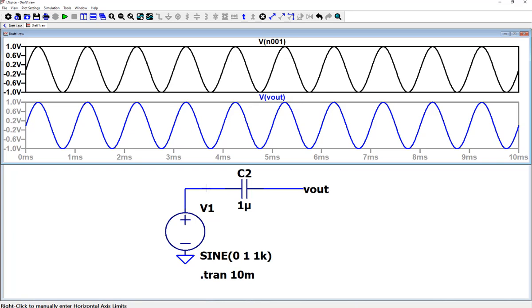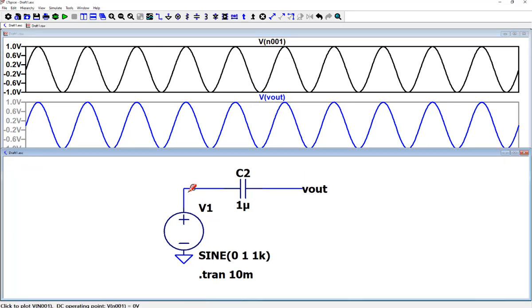If you add a resistor, there will be a phase shift. Now we can do the calculation. This is from circuit 1. But there won't even be any phase shift. It's just exactly the same amplitude, same phase. So the way that works is whenever it's charging up over here, it's pushing charges over here. It's expelling the same amount of charges to this terminal as well. Okay, that's why it's getting current flowing through the capacitor. It's actually not going through the cap. It just looks like it's going through the cap. The charge is just going in and out of the plate of the capacitor.